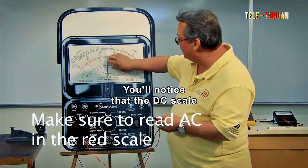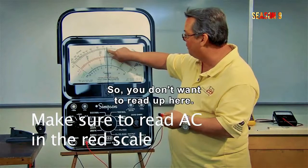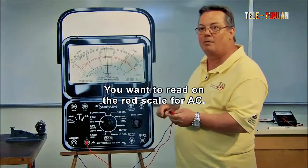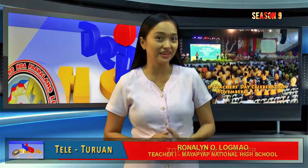You'll notice that the DC scale is slightly off from the AC scale. So you don't want to read up here. You want to read on the red scale for AC. Okay, now you know how to read the multitester.